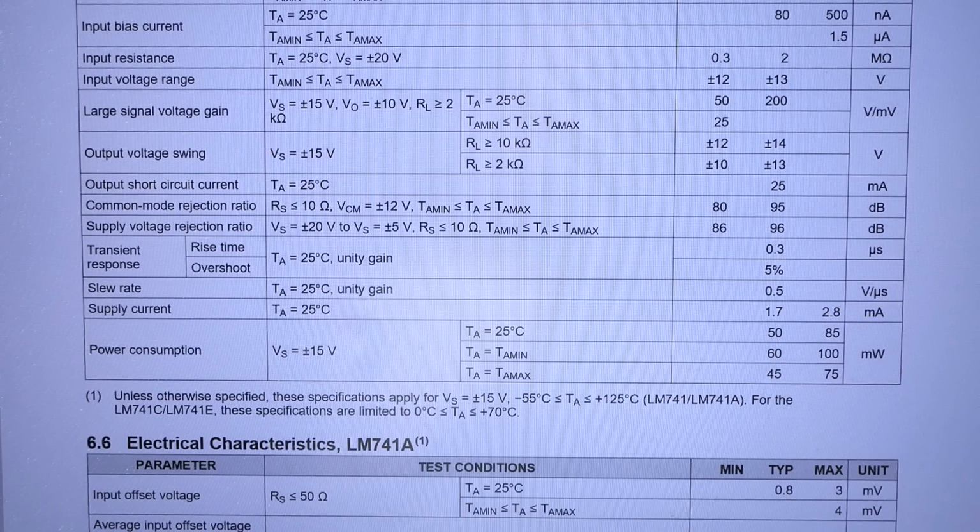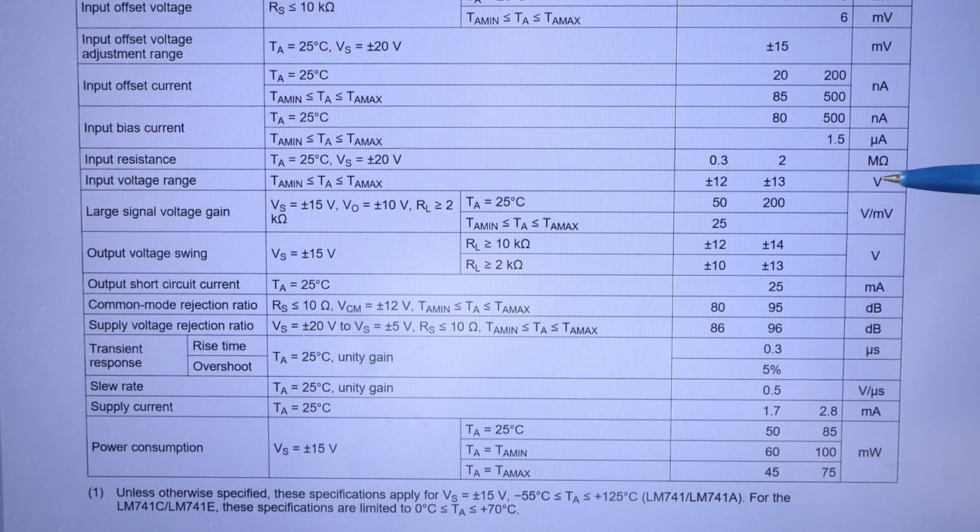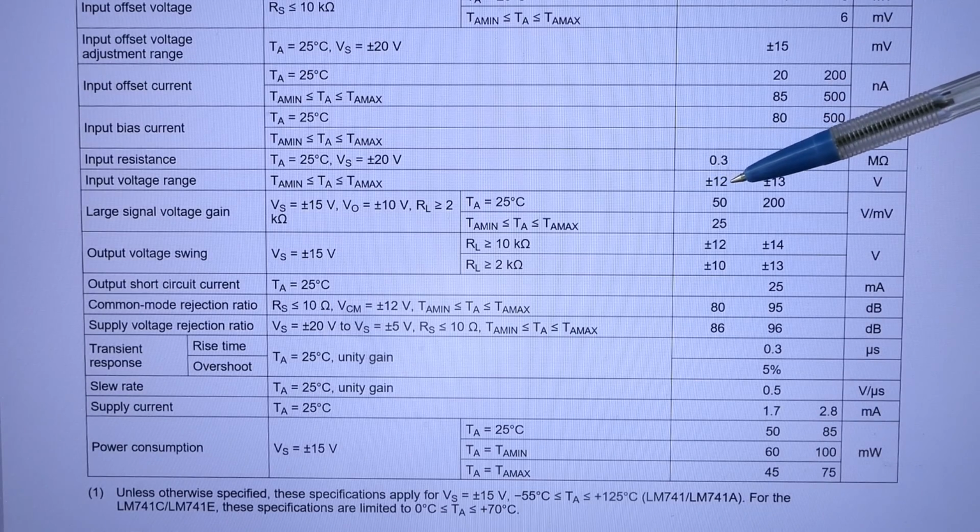If you don't need the OpAmp to be very fast, if you don't work with high frequencies, the most important things are probably the input voltage range and the output voltage swing. And this basically means the inputs have to stay away at least 3 volts from the supply rails. And this is also why this OpAmp can't work in my battery analyzer, besides the supply voltage range.